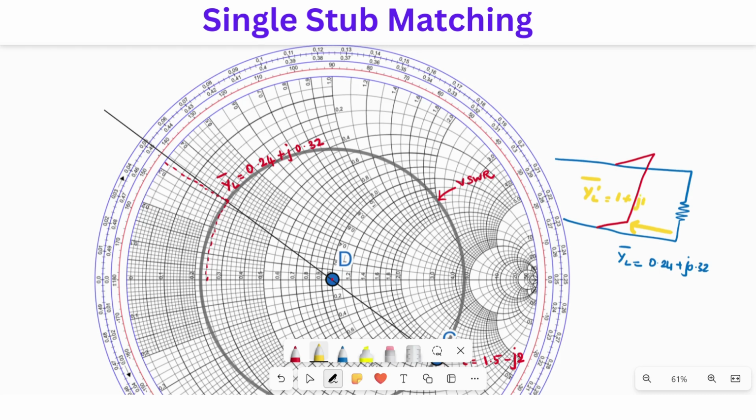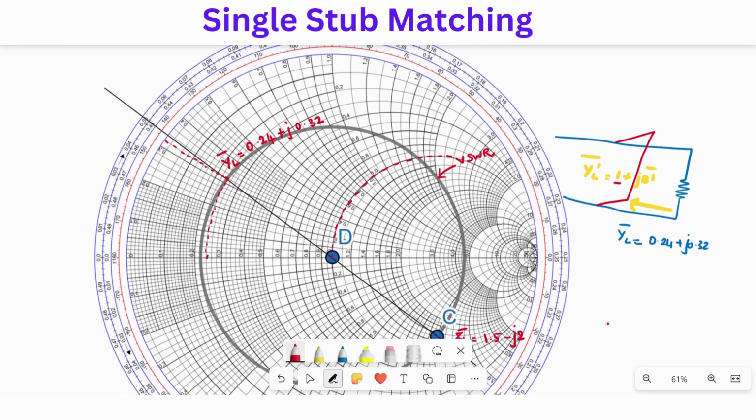You may get some susceptance value, which is not certain, but the conductance value should be equal to 1. Conductance value 1 means the resistance circle value should also be 1, right? So I'm going to highlight the resistance circle right here. This is your resistance circle, which is 1. If the load admittance should change to 1, then obviously the point should fall on this conductance circle, and I'll also highlight it in the downward direction. So this is our unity circle.